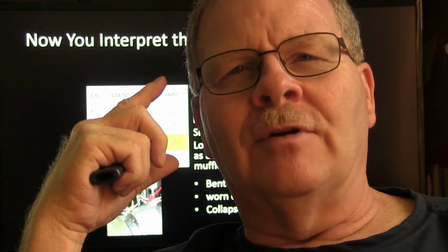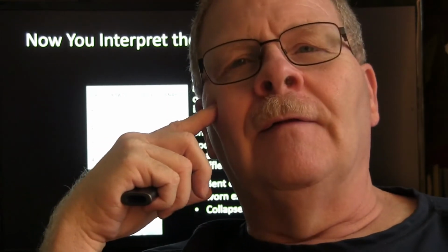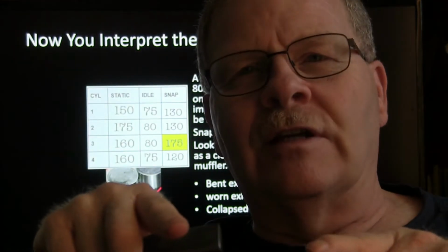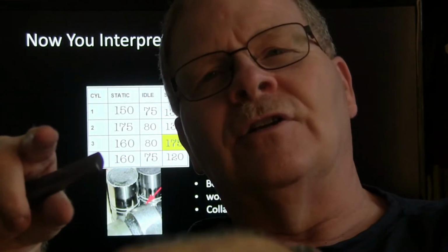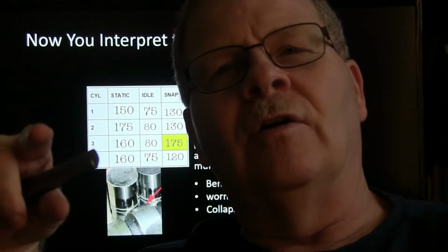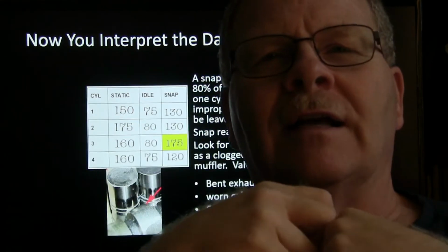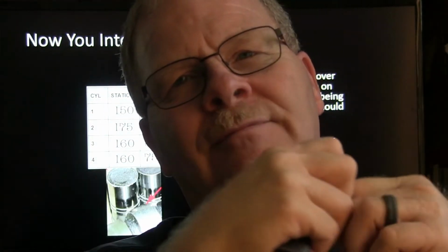And we pulled the intake off and got the lifters out of it. Incidentally, if the lifters are mushroomed on the bottom, you got to be pretty crafty to get them out of there. There's a little trick where you pull the lifters up, the ones that won't come out, and hold them up, and then bring the camshaft out the front after you get the timing cover all off. And then what you do is cut you a piece of an antifreeze jug and stick it in there under that lifter and push it down so that antifreeze jug will flex, and then when you get it pushed all the way through, you can pull the antifreeze jug part out, and that'll give you your little lifter that you were trying to get out of there.